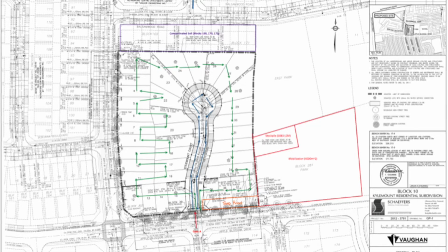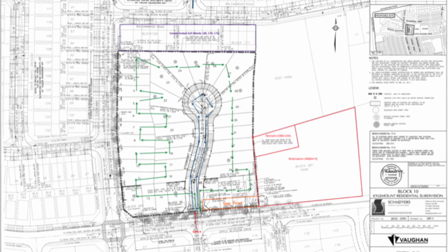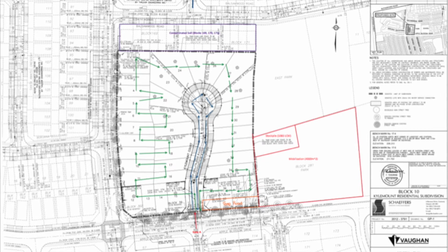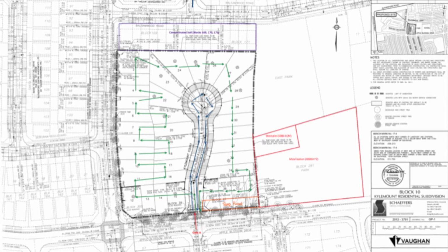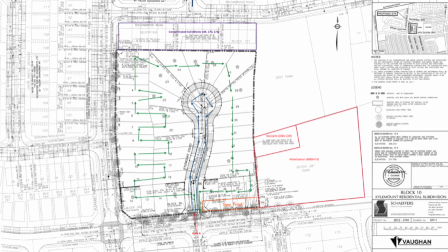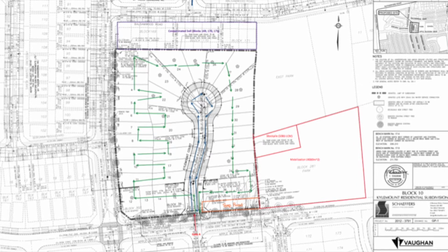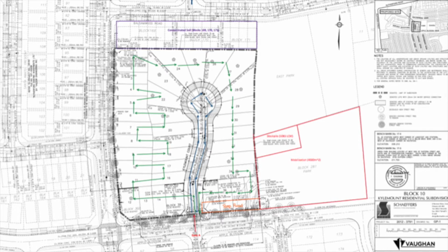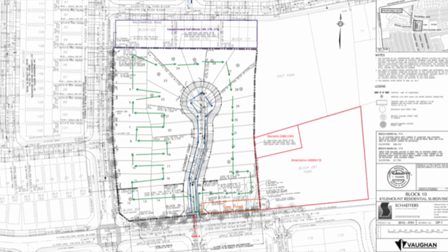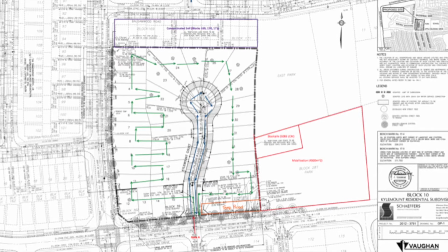We will begin with our approach to the layout of the construction site. All traffic will enter the site from Gate A, which is located at the red arrow. From the gate, a temporary road will be installed to the park, which will become our mobilization area. This area is outlined in red on the drawing. We have chosen this as our mobilization area because it provides sufficient space and is close to the entrance, which will minimize the distance traveled by equipment.